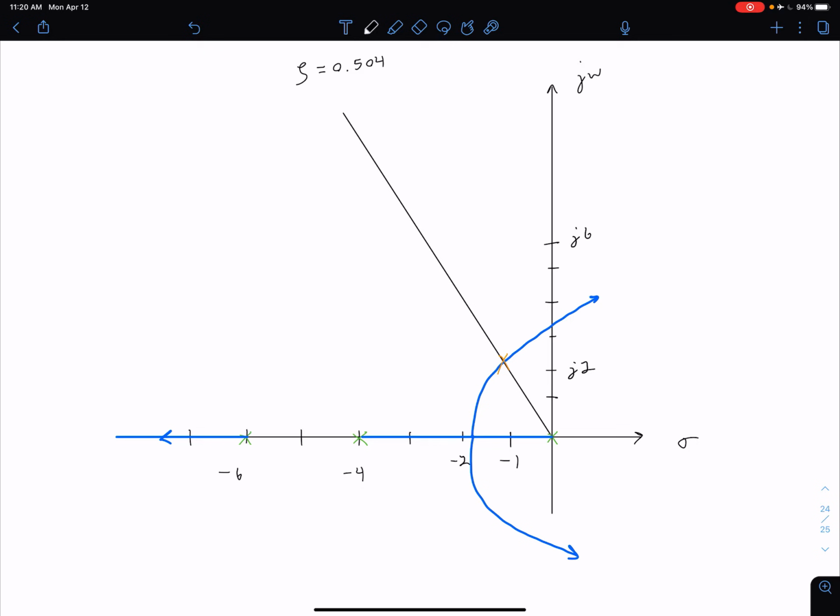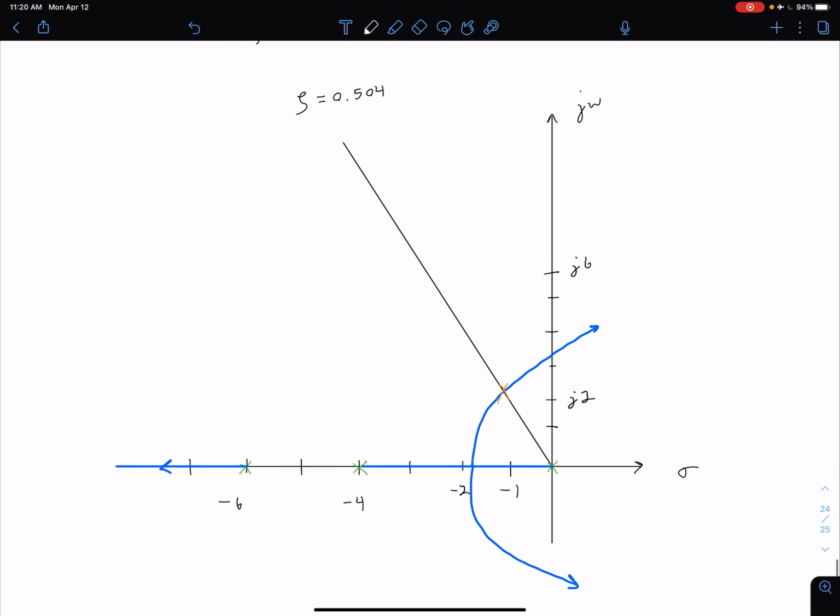Now our desired pole location we're looking for is at -3.6. This is where I've messed this up a little bit, but we can fudge our scale. So this is our desired pole location up here, around -3.613 plus j6.193. Again, not quite perfect, but it should be a little above this j6 point and a little past halfway here. What we want to do is figure out our angles contributing to that desired pole location.